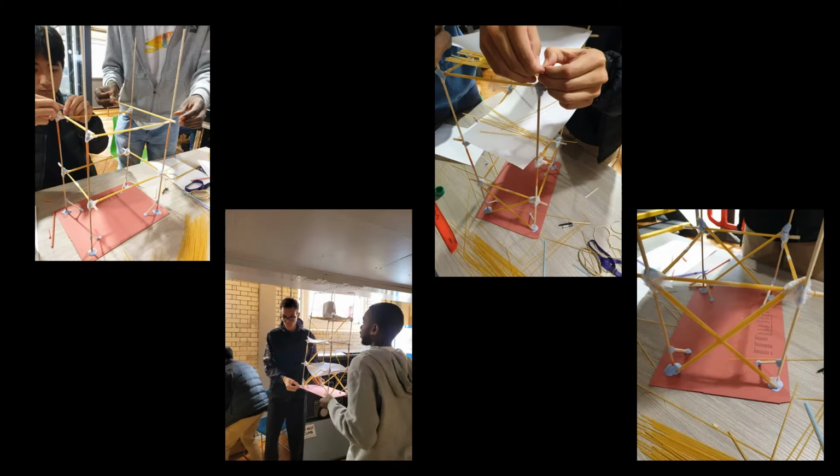In workshop 1, we will build a structure with dry spaghetti, wooden sticks, blue tape, and paper to resist a handmade earthquake. By using the knowledge we gained in the lecture, by adding bracing, strong columns and strong connections, we increase the stiffness of the structure. And this is the result.